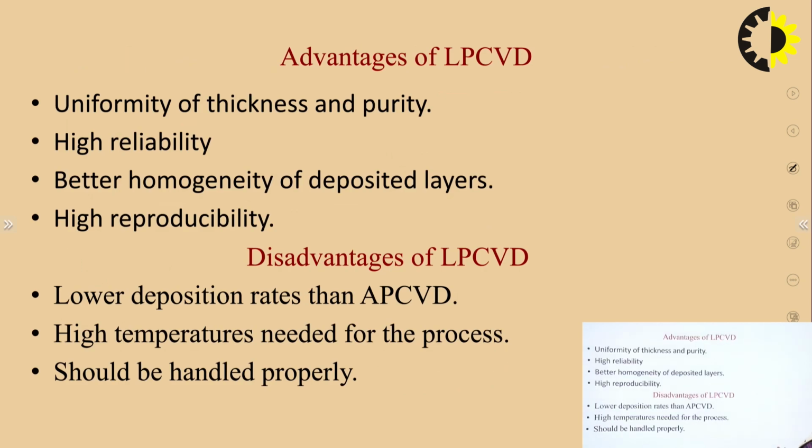Now, the advantage of LPCVD is uniformity of thickness. Basically it provides a uniform structure, high reliability, and better homogeneity of the deposited layer. It provides a uniform and homogeneous structure, and high reproducibility. That means such a method is quite usable in industry, because it has lots of advantages as compared to the previous method.